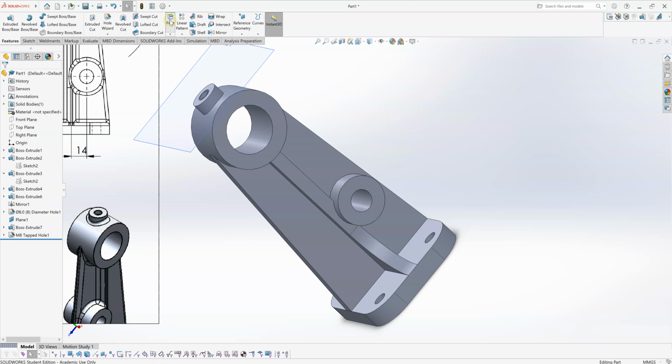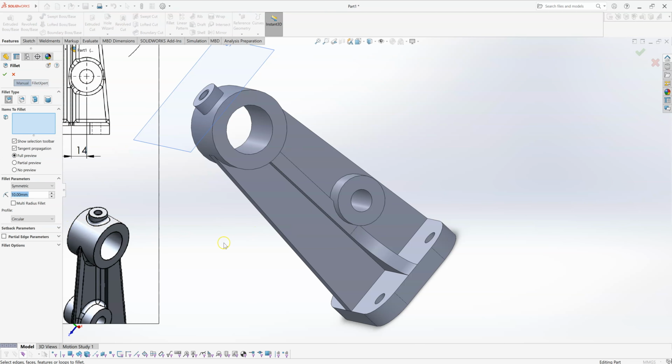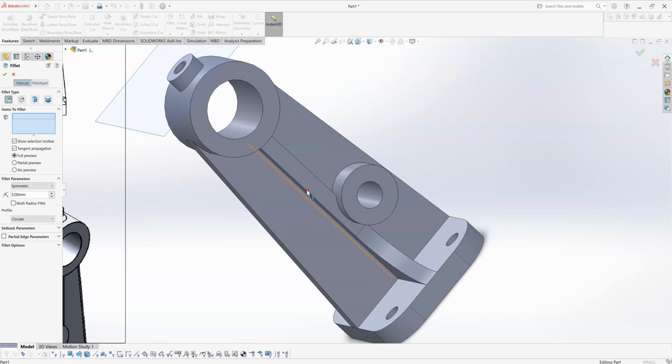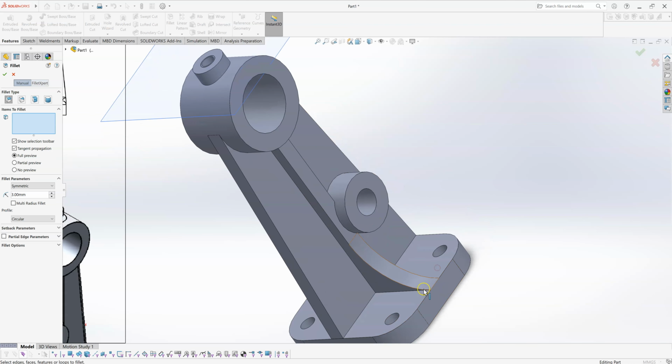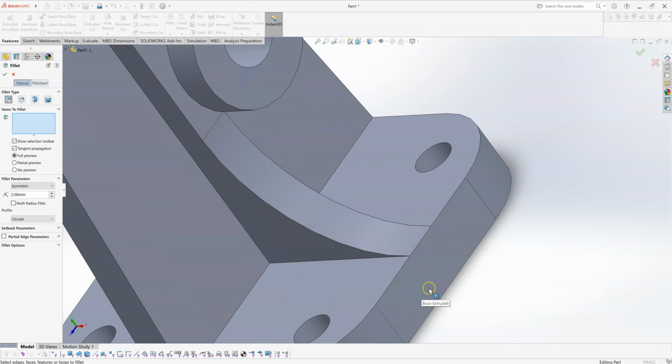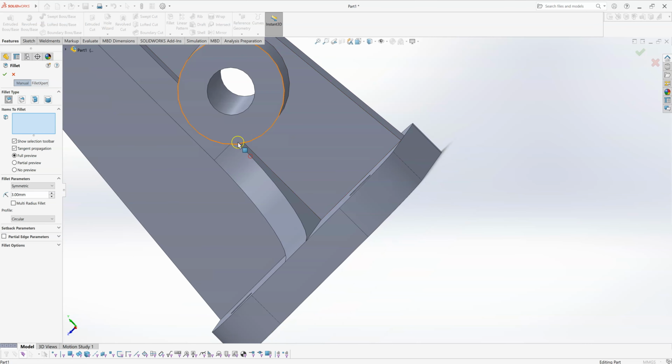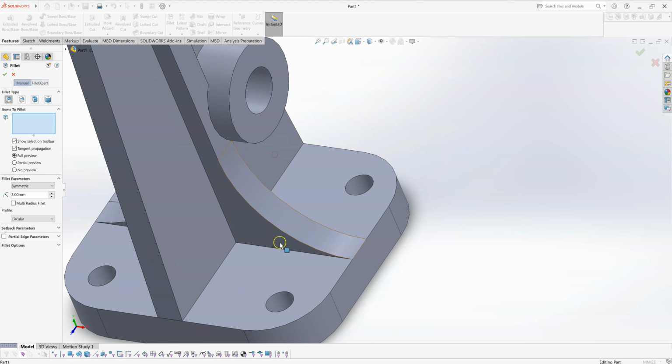Okay, so I'll use the fillet tool here. First of all, we want to set the radius of that to 3 millimeters, and the items to fillet here. So most of the internal corners here, let's say if I tackle this front web, this is one that may give you trouble, particularly the way this comes down to essentially 0 thickness down here, because this curve is tangent to the flat face down here. So I might treat this front web separately. It also has lots of intersections here with the cylindrical feature there. So we'll try that out and see what happens